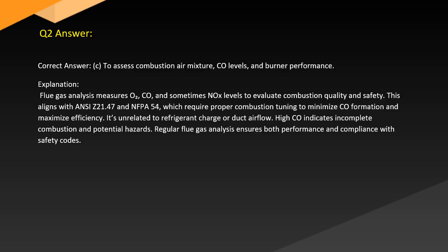Answer. Correct answer: C. To assess combustion air mixture, CO levels, and burner performance. Explanation. Flue gas analysis measures O2, CO, and sometimes NOx levels to evaluate combustion quality and safety. This aligns with ANSI Z21.47 and NFPA 54, which require proper combustion tuning to minimize CO formation and maximize efficiency.